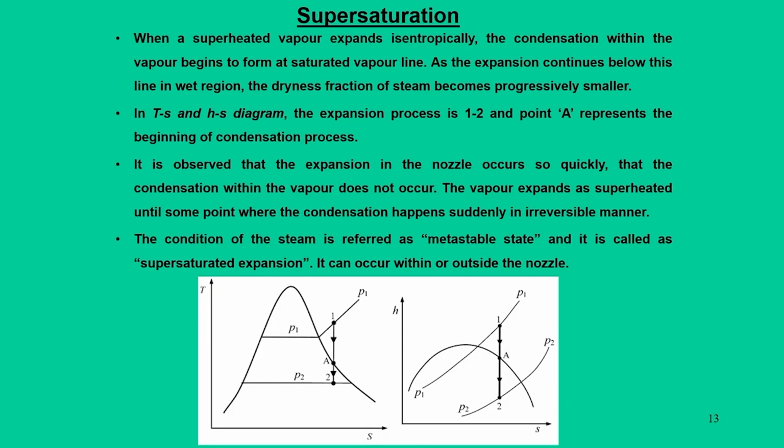Now, moving further, for steam nozzles, when you think about the expansion in the nozzles, another practical phenomenon that comes in is what we call supersaturation. A similar term, supersaturation, is also encountered when dealing with steam turbines. Of course, for the sake of continuity we will look a little more at what this state is, because supersaturation is an irreversible phenomenon and normally it is called a metastable state.